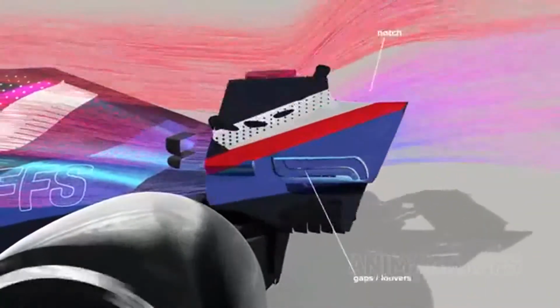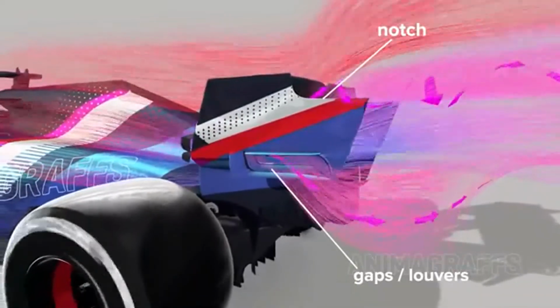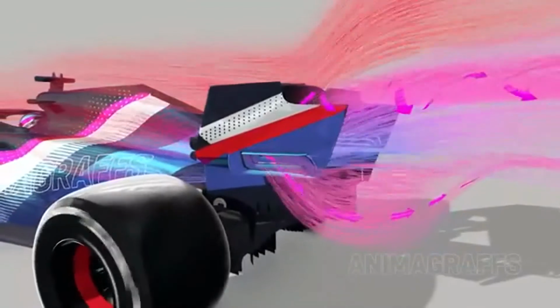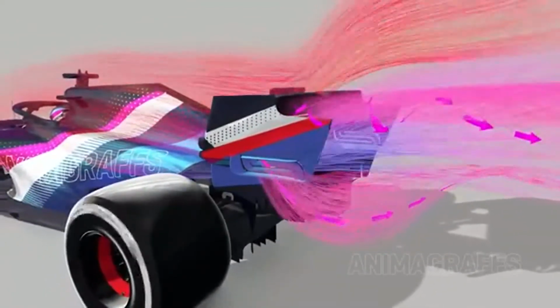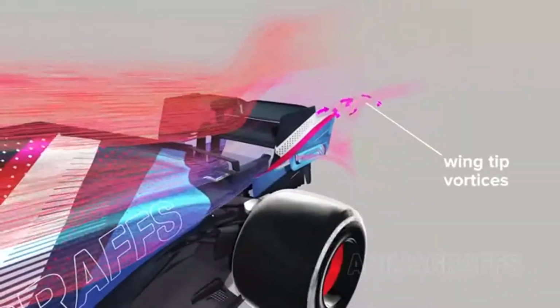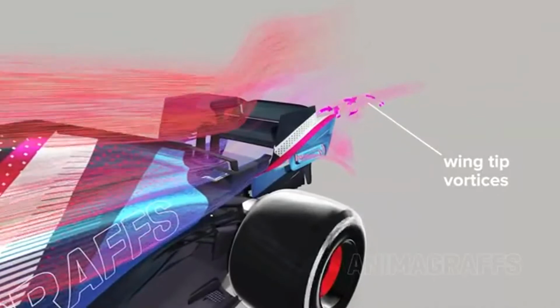The upward curved rear wing, which is another critical downforce generator, has notched end caps with gaps and louvers to allow some air to combine early, altering and shaping rear wing vortex characteristics. It's also where, in wet conditions, the noticeable misty wingtip vortices sometimes appear in plain sight.